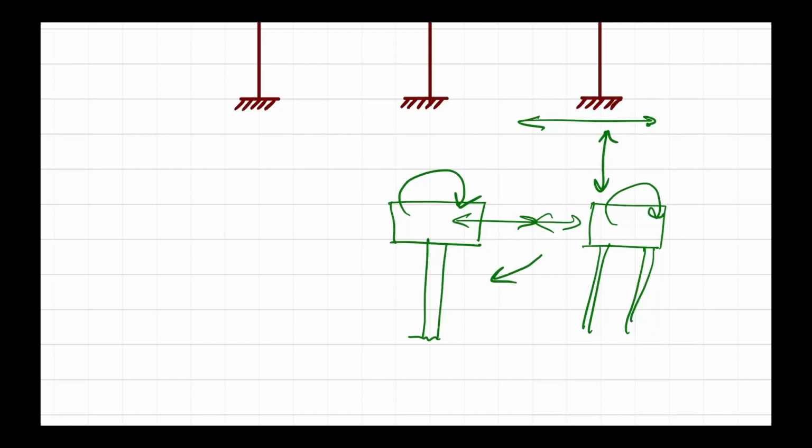But in general, for a small building, you need just 1 pile. And you don't utilize the full capacity of the pile, because you just need something to come down to the stratum level or the bedrock level to prevent the settlement, and that's it. In Thailand, we use piles sometimes with really large sizing, like I-26 or square 26, because in some areas the soft clay thickness is somewhere around 24-25 meters.